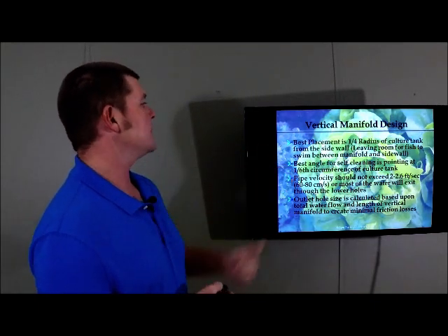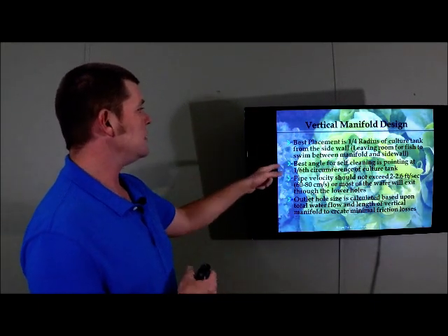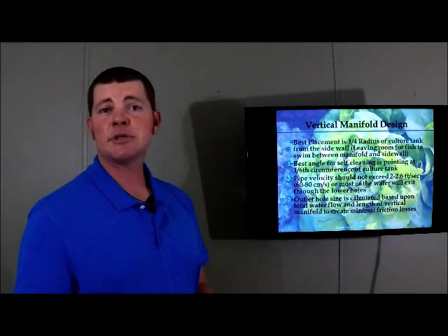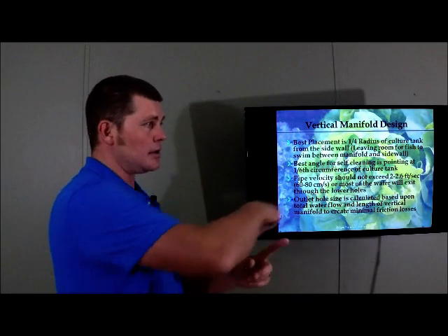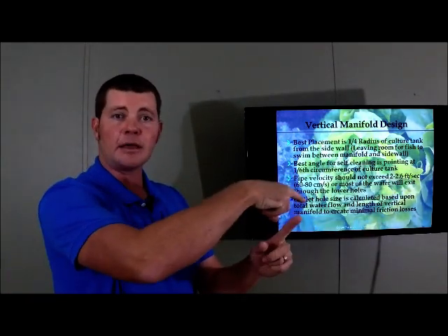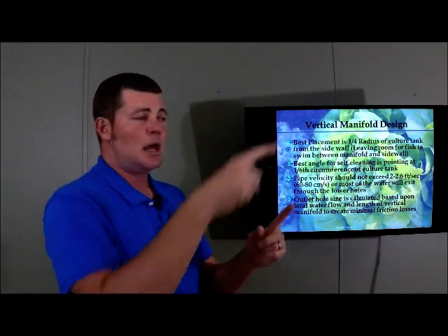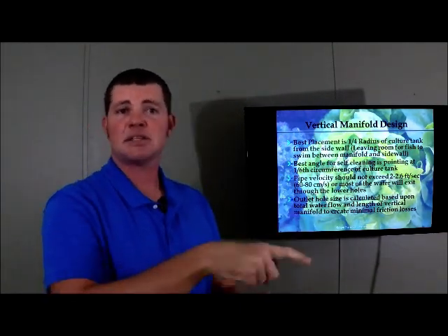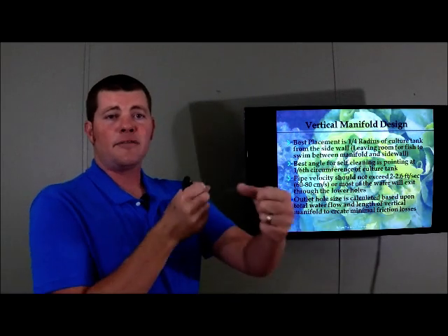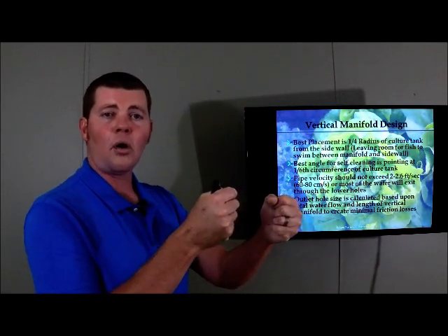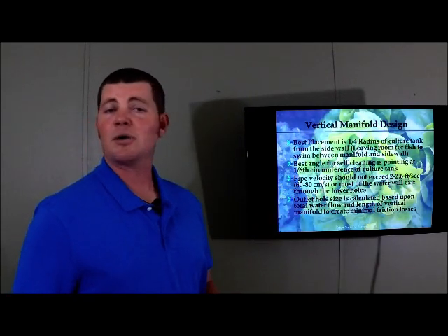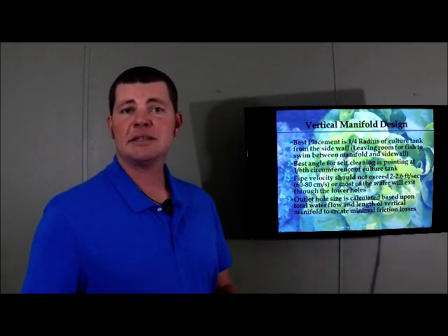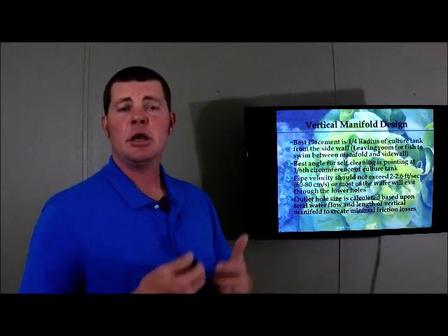The best angle for self-cleaning is if you point the injection stream at 1/6 the circumference of the culture tank. So if you take the entire circumference of the culture tank and you divide it by 6, that distance is where you want to aim the jet stream to create the fastest rotation within the tank. Now, if you rotate it closer to the wall, you're going to slow the rotation while keeping the same water turnover in that tank. So you're still going to process ammonia just as fast.